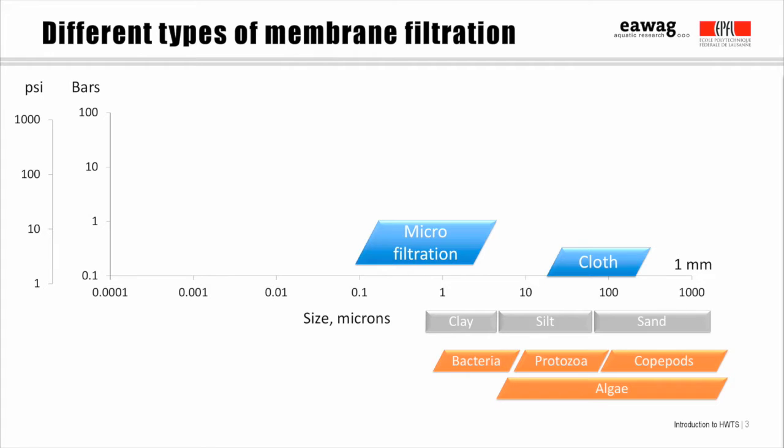By the way, let's talk briefly about units of pressure. The atmospheric pressure at sea level is 100 kilopascals, which is commonly called 1 bar, or 1,000 millibars. Now, 1 millibar is roughly equal to the pressure caused by 1 centimeter of water, so 1 bar, 1,000 millibars, equates to about 10 vertical meters of water. 1 bar is also equivalent to 15 pounds per square inch, roughly, if you prefer PSI units.